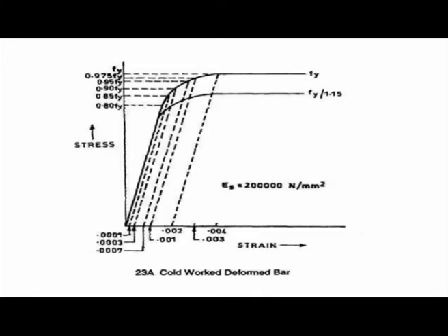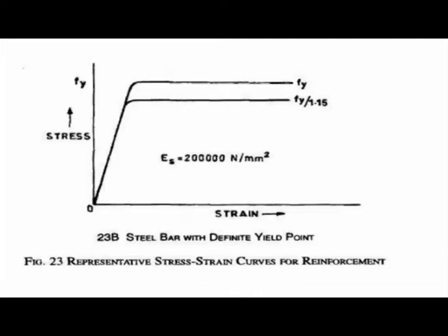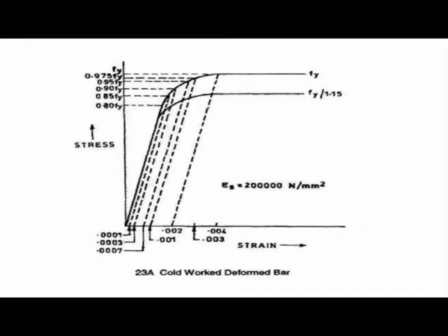In the earlier case we provide the reinforcement at the bottom, and that is actually called a singly reinforced section. Now if there is a depth restriction, then what reinforcement do I provide? As I have told you, we cannot increase the section here, so we have the section like this, and I have to provide another reinforcement at the top.